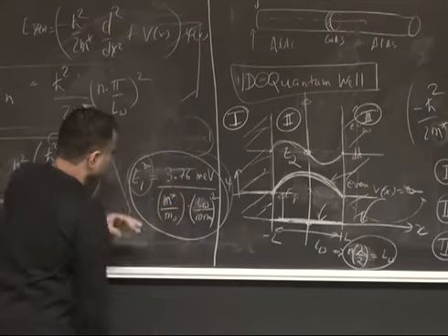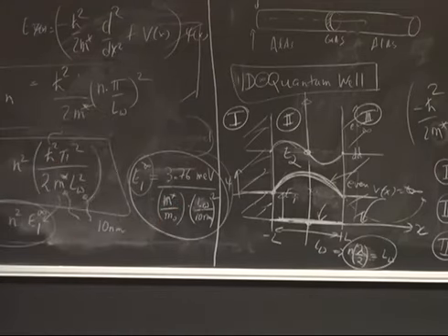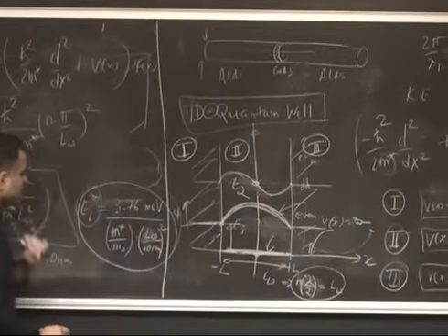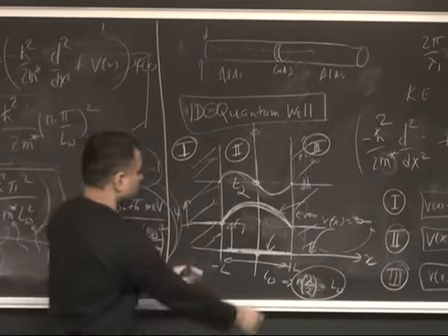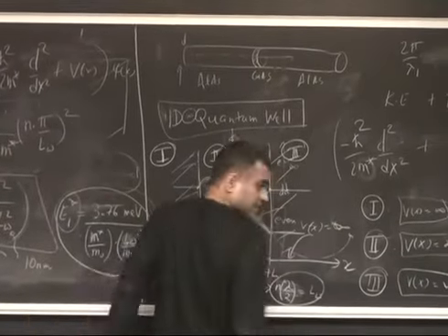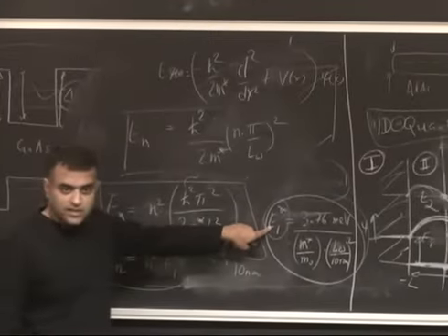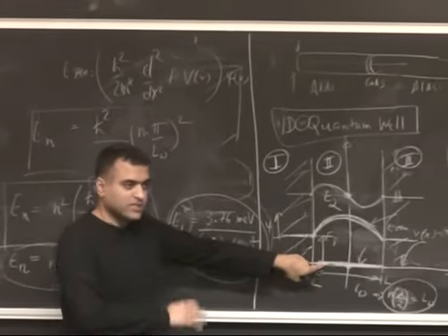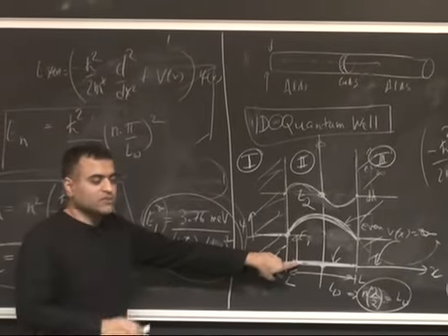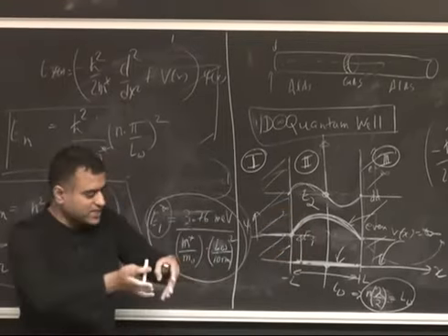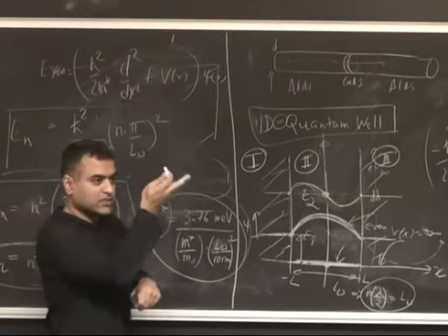But essentially, because of confinement of a layer like gallium arsenide, you can see, right? One very good way to look at it is what will happen if I make the quantum well wider and wider and wider. As you go wider and wider, this will gradually go to 0. It will merge with the free electron solution, meaning the ground state energy is 0 if you have an infinitely large well. And as you squeeze it, it goes up as L squared. The ground state energy floats up.